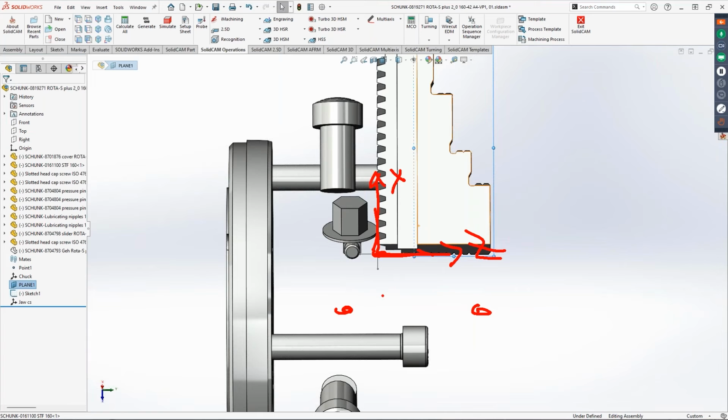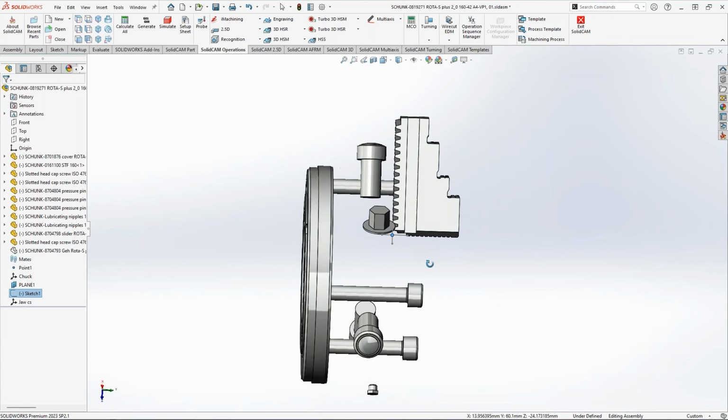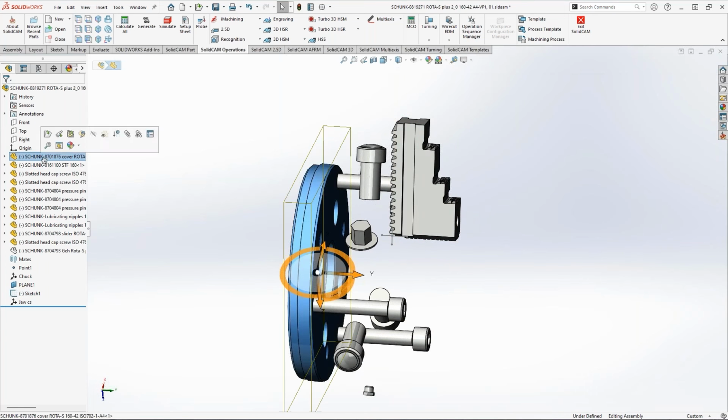a rule, but if you really want to get a correct reference point, which is important in case you want to do internal clamping of the jaw, then the rule is quite simple. To detect this point, we first go along the X, we find this line, and then we try the first Z. The first Z geometry that we pick, in this case, will be this point over here. So I have made these helping lines just to detect this joint, so it's easier for me later. But you will agree with me that there is nothing so special about it.